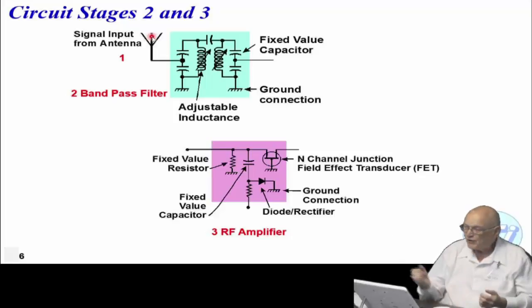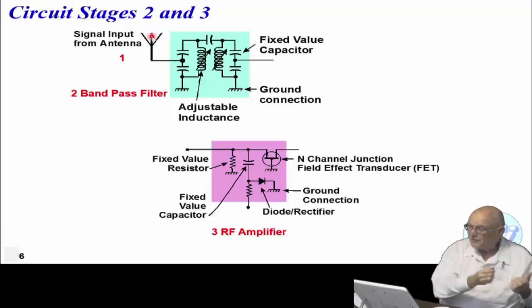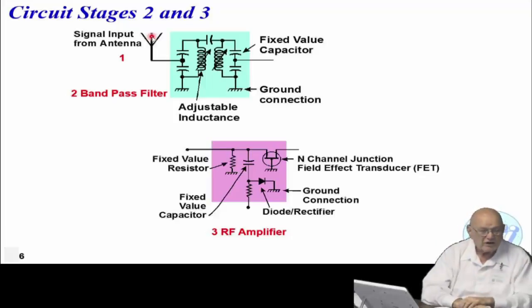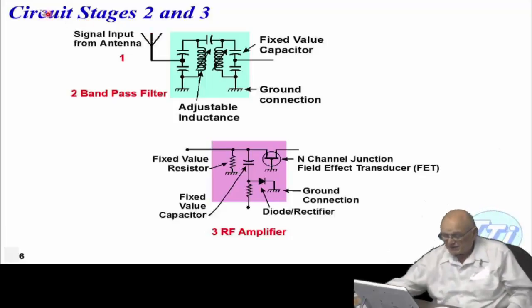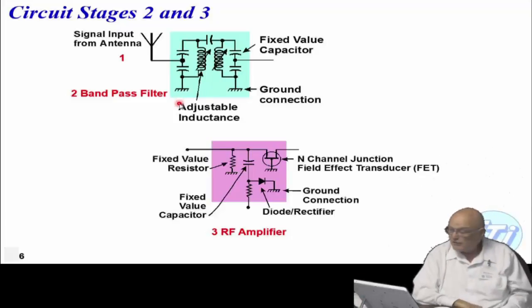So that means if you hook up a 75 ohm coaxial cable to a 50 ohm system, you're going to get what they call an impedance mismatch. So these are some of the terms that you need to know. Right here, that's got that 377 that matches with what this circuit is. And this part of the circuit, see, it's a tuned circuit. You'll learn how we do that at the end of the day with the actual impedance matching circuits, or resonance circuits, that we'll be using.